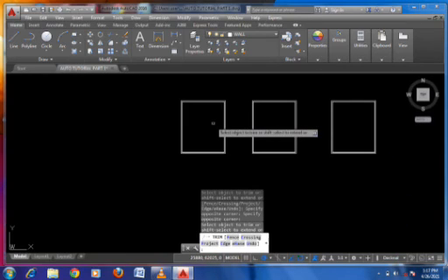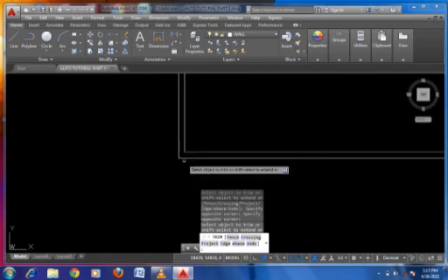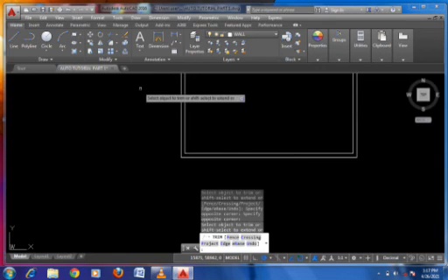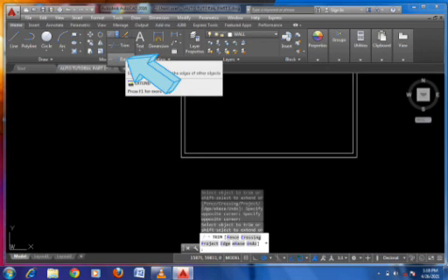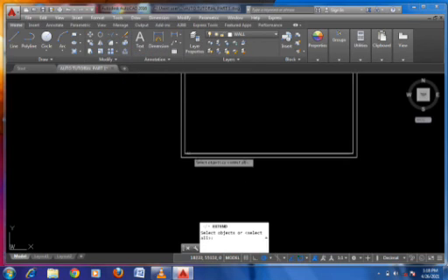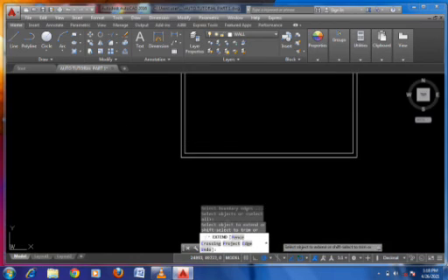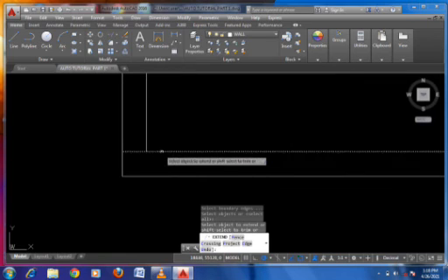So now the other thing I'll be showing in this AutoCAD tutorial video is how to take back what I trimmed to how it was before by using extend. I'll just extend the line. Just go to the trim tool. They are like opposites. So trim is the opposite of extend, and extend is the opposite of trim. So I'll just click on my extend. Once it says select object, I'll press enter.